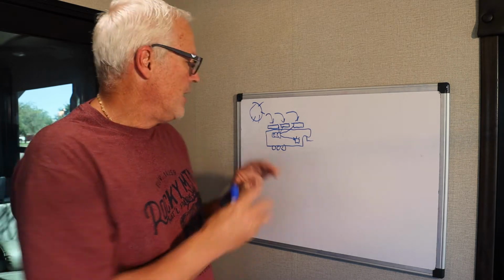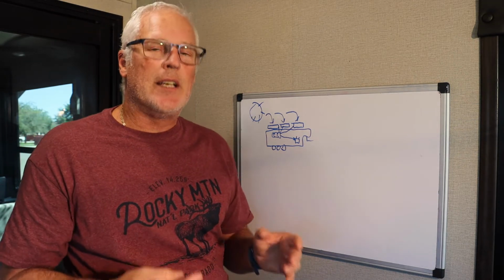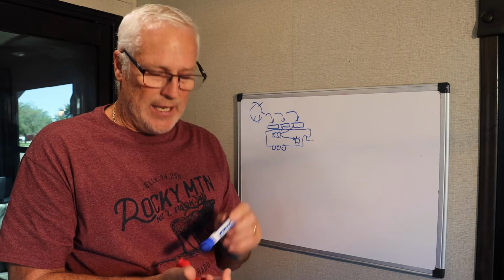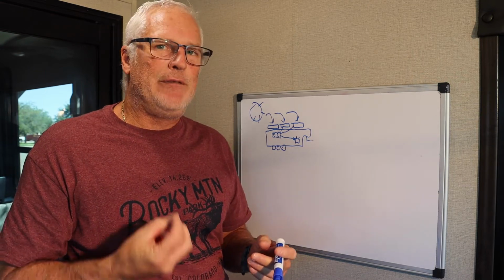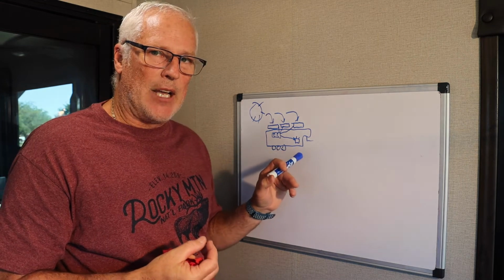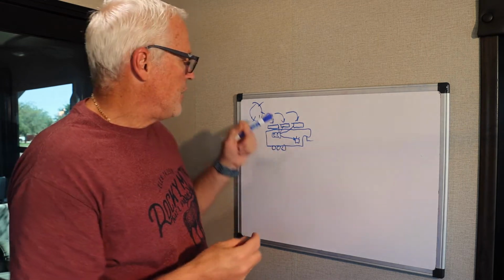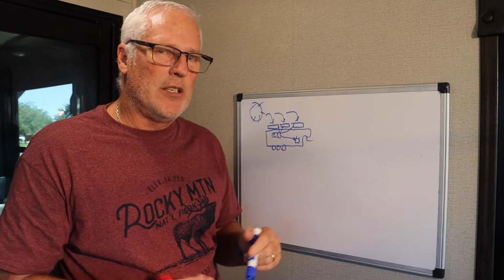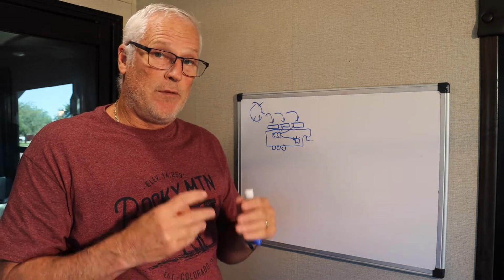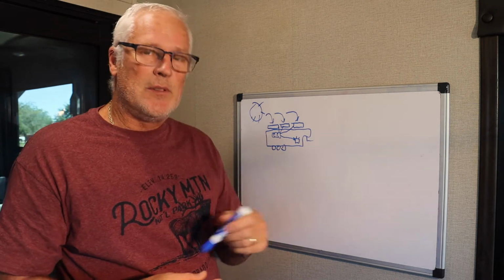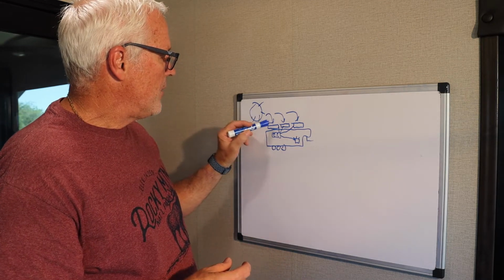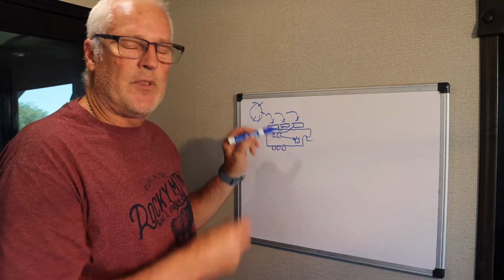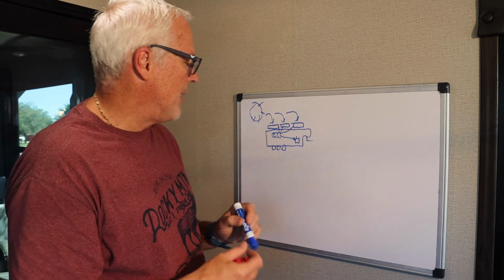and its whole purpose is to charge the battery. Now what the charge controller really does, it's a pretty smart box. It's used to charge your RV battery as quickly and efficiently as possible. If you think about it, if these were tied straight to your battery, that's not good. If a battery is already fully charged and you keep trying to charge it some more, that's not good for your batteries. So solar panels go into a charge controller, which goes into a battery.